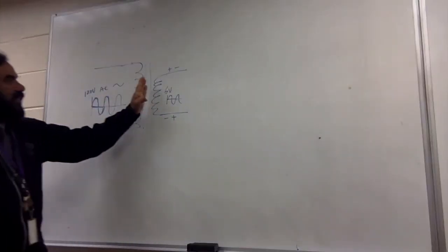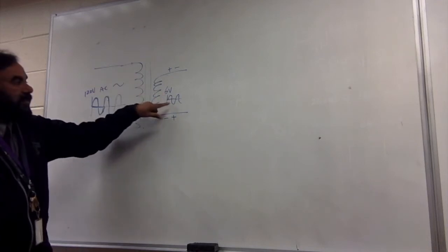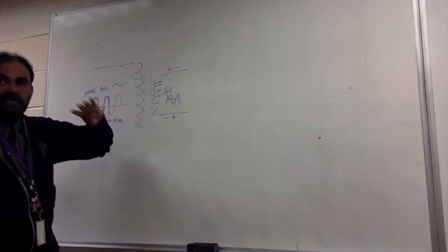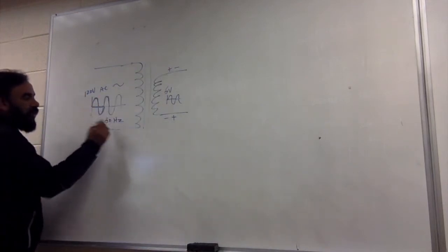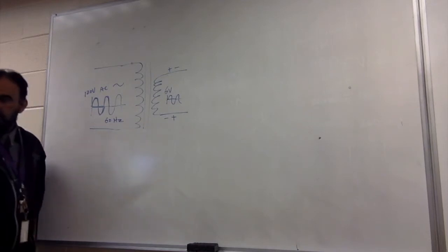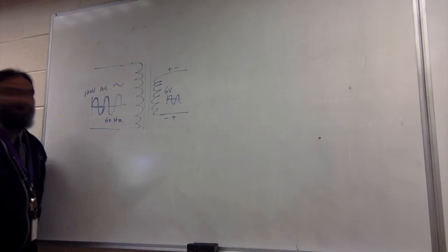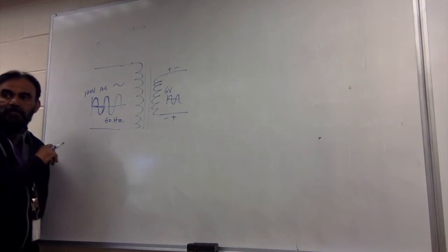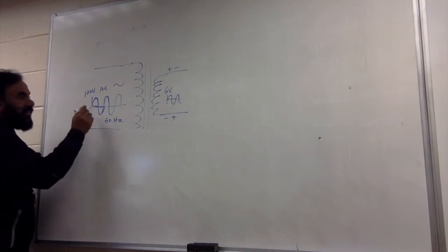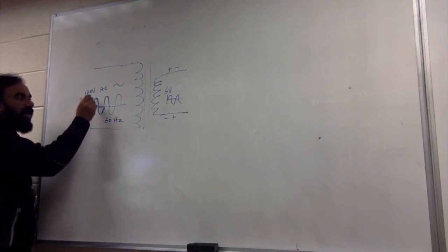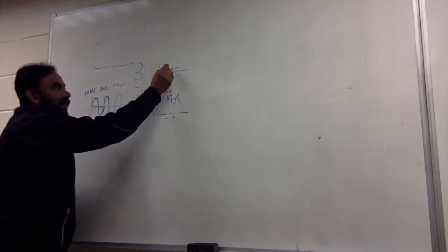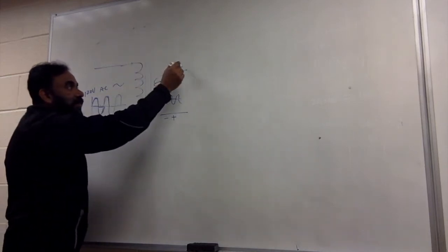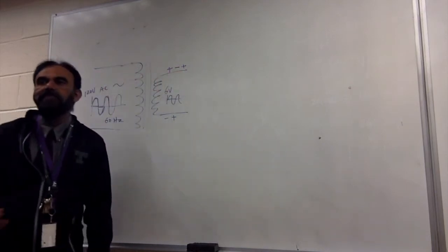When you have the transformer, it only transforms the voltage, but the signal still stays AC. And AC means it fluctuates between plus and minus and plus. Every cycle changes. The time from here to here is 1/60 seconds, which is 0.0166. So the time from here to here is 0.008 something. For 0.008 seconds it remains positive, and for the next 0.008 seconds it is negative, and then the next 0.008 seconds is positive, and like that, it flips. It's a very little time.